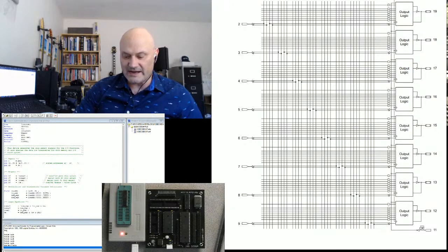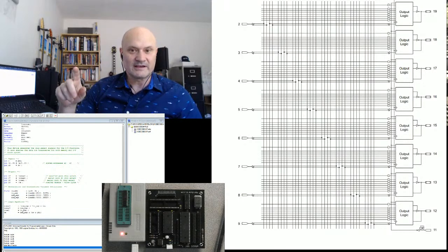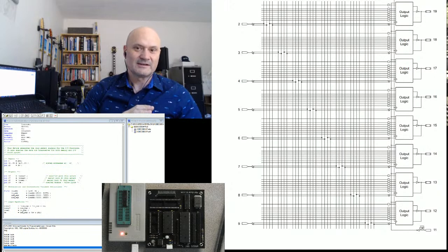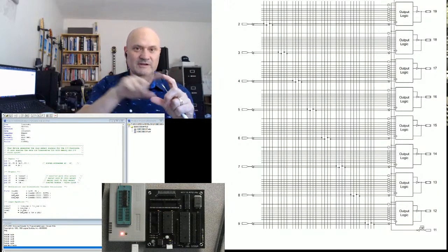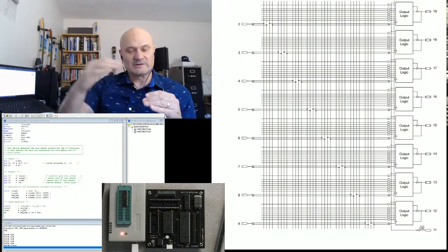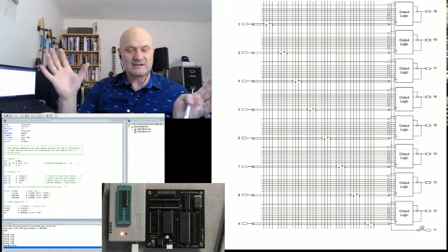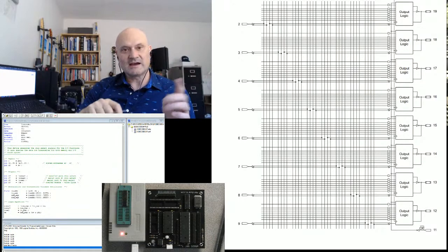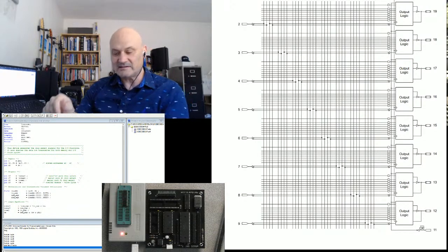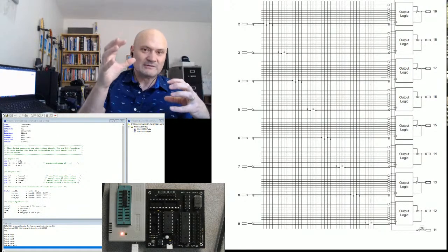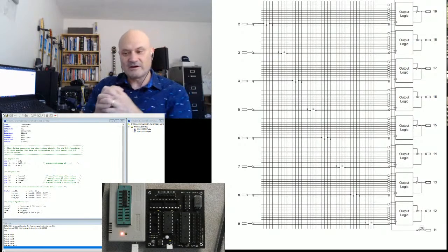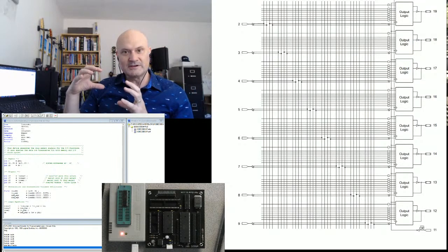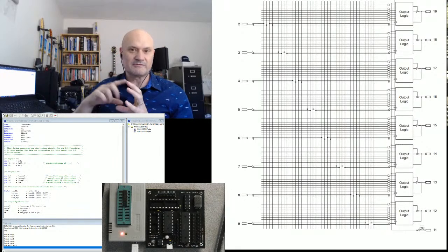Right. So you can synthesize a state machine using something like a Johnson counter or a Gray code encoding. A Johnson counter is a row of flip-flops with a feedback loop, and it goes through a set number of states, and each state can then be decoded. So that's like using a counter and a multiplexer almost. And then the other kind is simpler and uses a bunch of flip-flops with feedback.